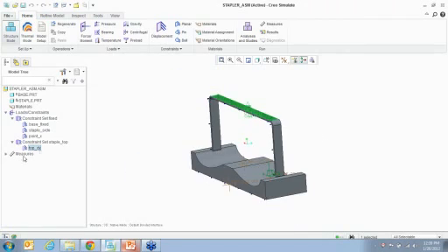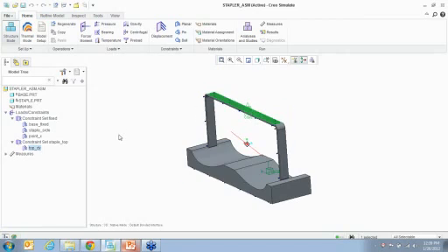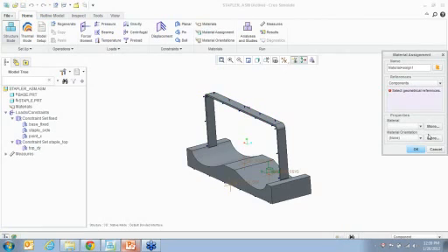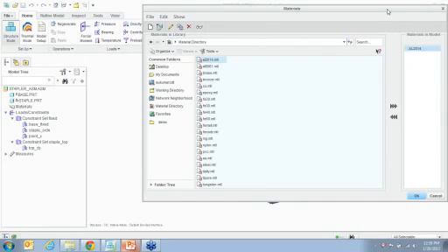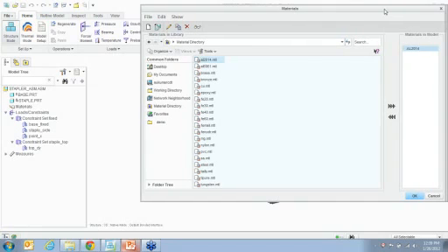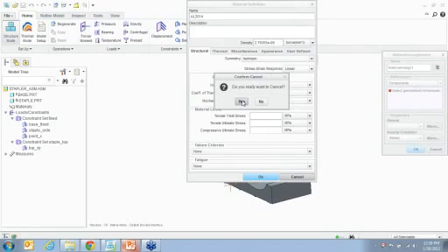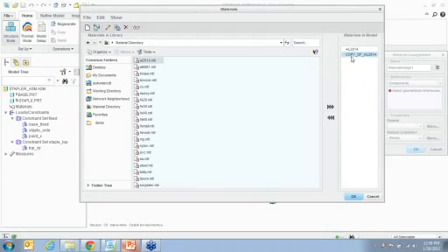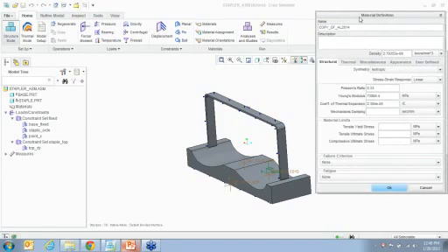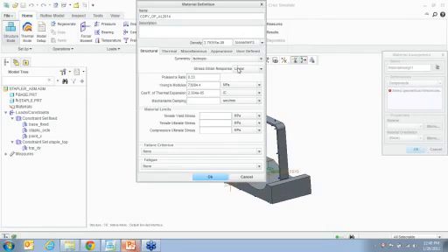So within here, I'm going to go ahead and add a material property. So material assignment. Say I use aluminum. You can see this is aluminum. And then I'm going to make a copy of it. Go to the properties of it. And notice this is an isotropic linear. So I want to change it to elastoplastic.